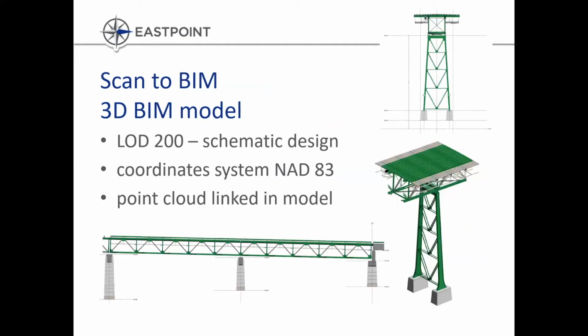We agreed to model the bridge to LOD 200. There's one of those acronyms again, LOD. LOD in the BIM world means level of development, and LOD 200 is schematic design. This means we would model all the major components and elements that make up the bridge as defined by our client, Halifax Harbour Bridges.